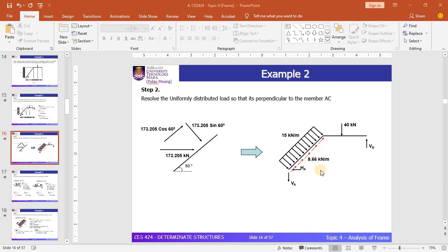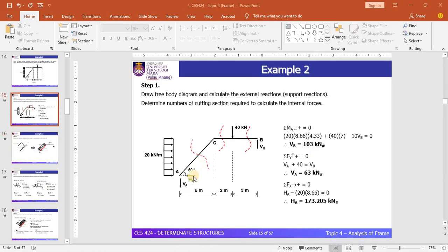Okay, so the next step, you can get the equation of moment, shear force, and axial force for each cut section. I think this is the new thing that you have learned in this slide, which you didn't learn in the previous, meaning during the diploma, if I'm not mistaken, this is not included in your syllabus. Okay, so I hope that you can figure out how to convert the UDLs into a local axis. So basically, this is a global axis.